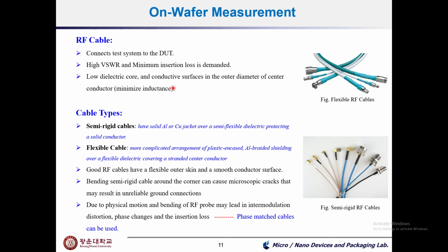The RF cables are important components in our measurement system, whose main purpose is to connect the test system to the device under test.